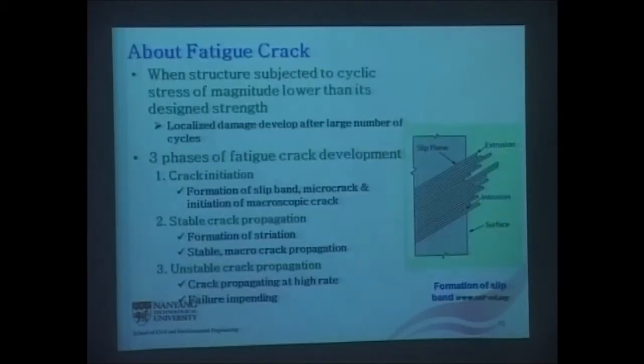So, all right, fatigue. I think most of you know what this is, so I'll just say it quickly. Basically, there are 3 stages: the initiation, which is usually up to 67% of the life. Then once you hit the initiation, the propagation will pick up very fast, and there is almost instant failure after this stage. So these are the 3 stages that we try to pick up from experiment, numerical, and our semi-analytical model. From there, we can do the predictions.